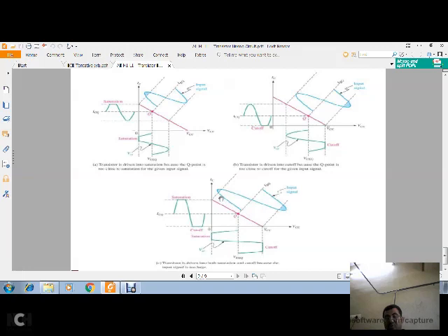If you go beyond 50 millivolts, say 51, plus 1 millivolt, this is 50 where it should be, but if you are applying 51 millivolts, it crosses its limit. You get a clipped output, in both the negative as well as positive signal. So this is not a faithful amplification. What it tells is that a transistor amplifier also has bindings. One needs to apply an input voltage of, say for example, less than 50 millivolts.